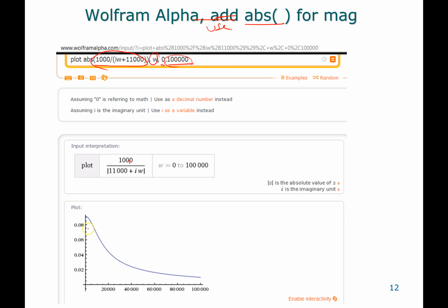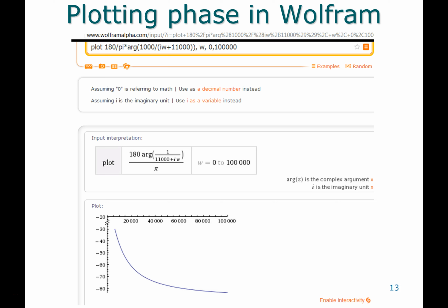And what's great, it'll actually display that for you, so you can really show the behavior, and you can even identify the cutoff frequency. It's going to be like 0.70, so it's going to be something like around here. That's going to be your omega 0, something there. And you can also plot phase in case you needed to.